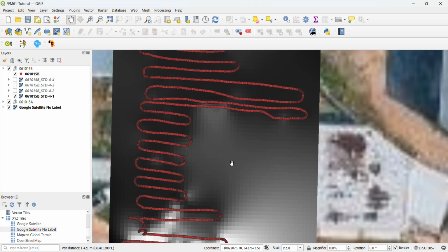Okay, with that said, let me show you exactly how to do that. So the first step is to create an area where we can tell the computer where we want to keep the data. To do that, I'm going to do the example on the B layer, and I'll probably again fast forward how I did on the A layer. Okay, first step, go to vector, geoprocessing tools, and then buffer.